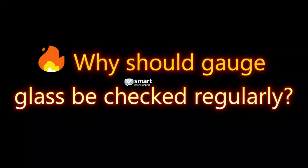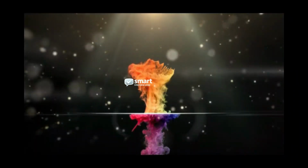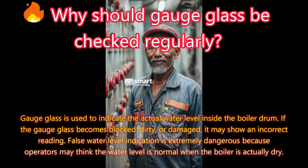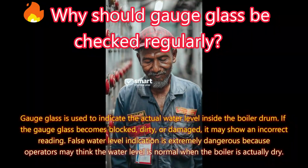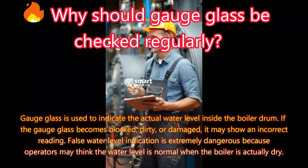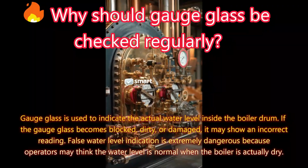Why should gauge glass be checked regularly? Answer. Gauge glass is used to indicate the actual water level inside the boiler drum. If the gauge glass becomes blocked, dirty, or damaged, it may show an incorrect reading.